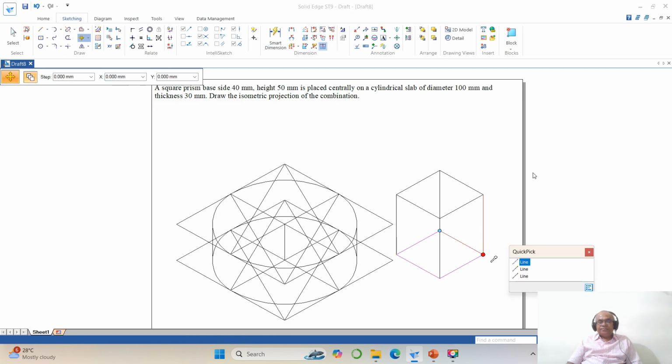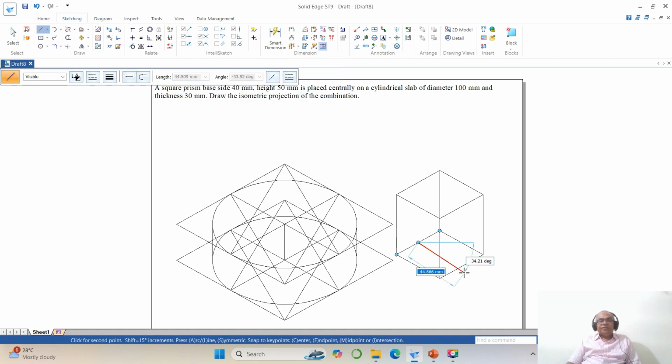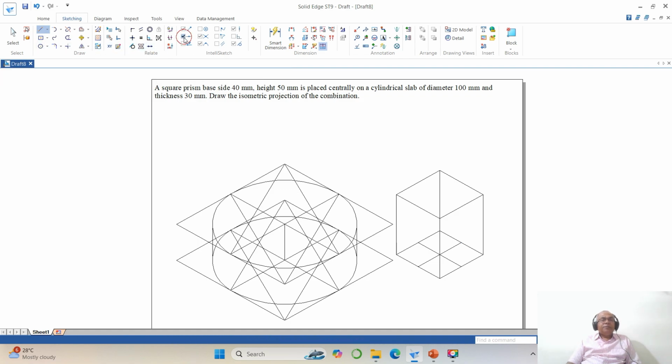Now I want the midpoint. Now you go for a line, enable midpoint. Mid of this to mid of this, sorry, go to line, take a midpoint of this to midpoint of this, similarly midpoint of this to midpoint of this, and you disable midpoint by holding the move, disable copy, select all these 4 lines and take these 4 lines.